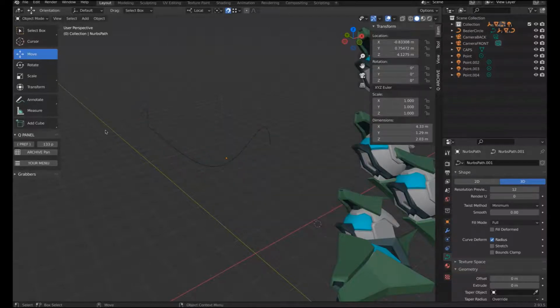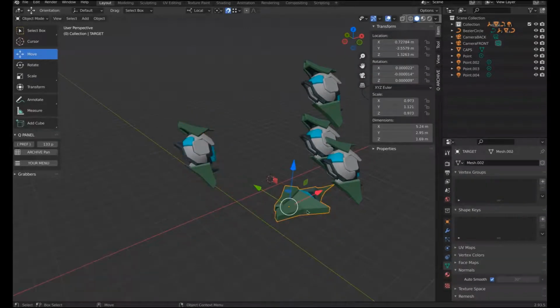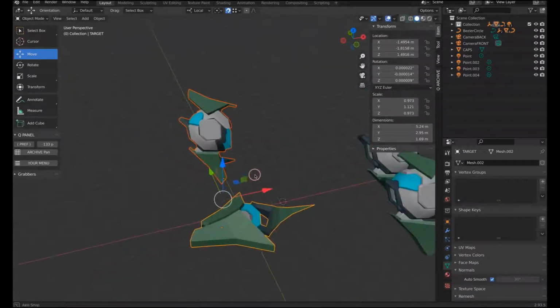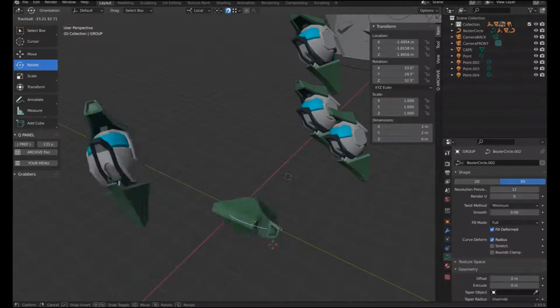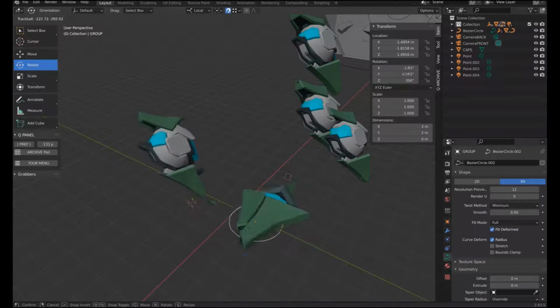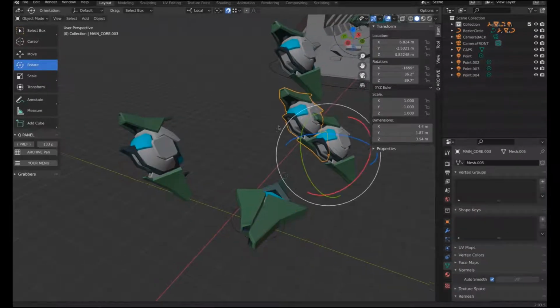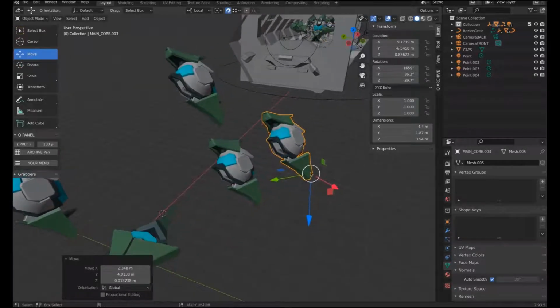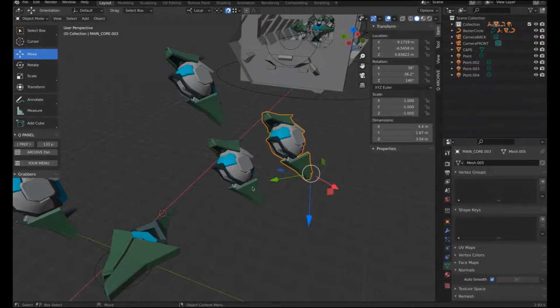Then group. We can spawn a couple of objects and group them. This is called also parenting, so you can get an object, select another, and set a parent. I usually use keep transformation. So there is one child and one father.